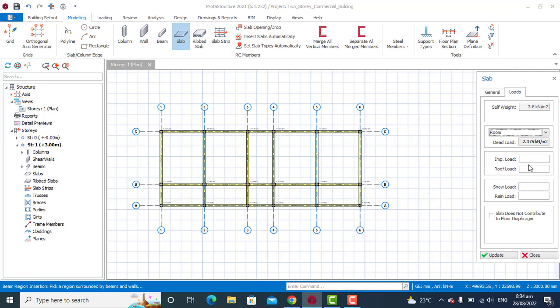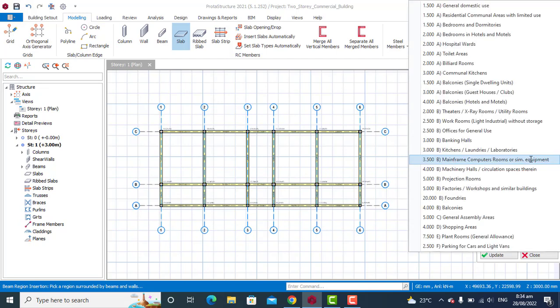And then the next thing to look at is the imposed load. So for shopping areas, the value will usually be 4 or 4.5. I can also give it a right click in here, and as part of the software design, you have some of the values already given by the loading values in our BS 8110 codes, the loading codes.